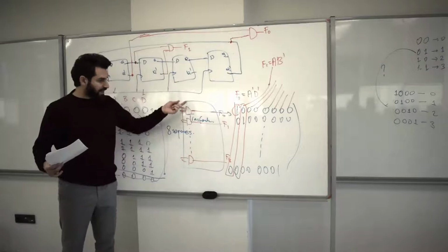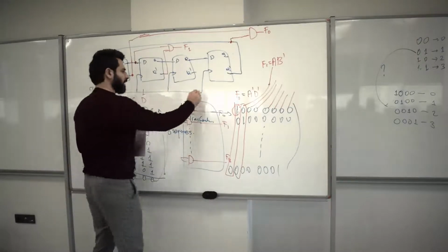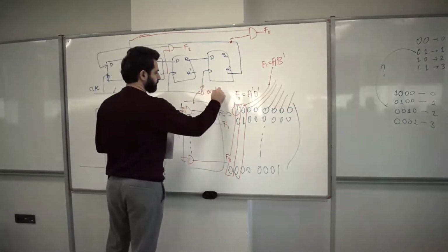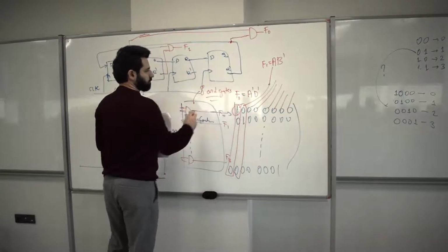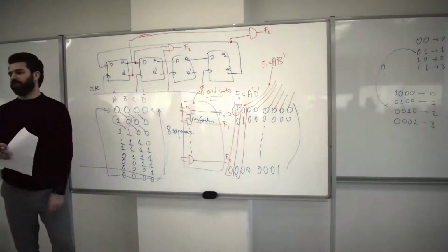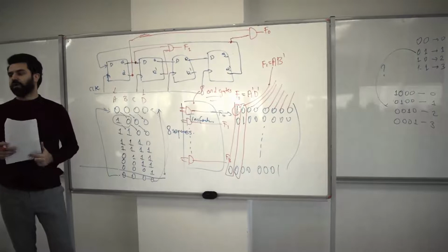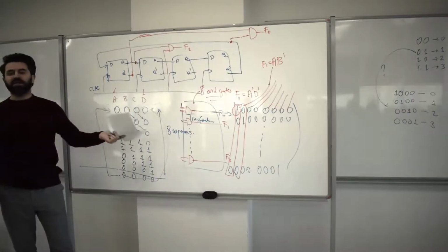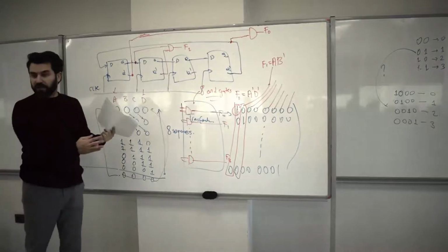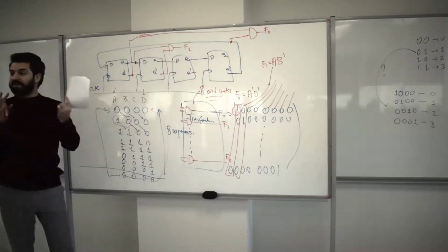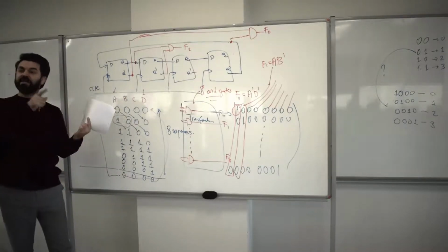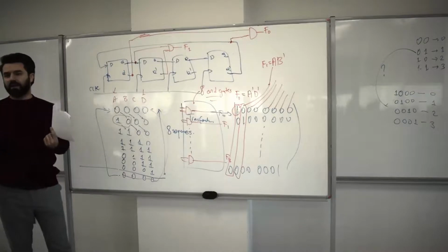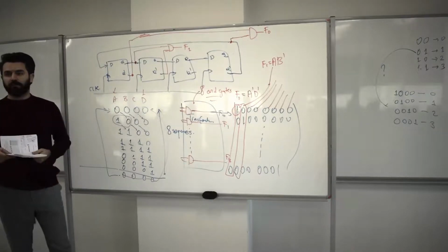In other words, we use 8 different AND gates here, to be able to generate a format that is similar to or identical to ring counter outputs. That is the price we pay. However, now you can enable 8 different modules by sending an enable signal to each one of them at a time at each clock cycle.